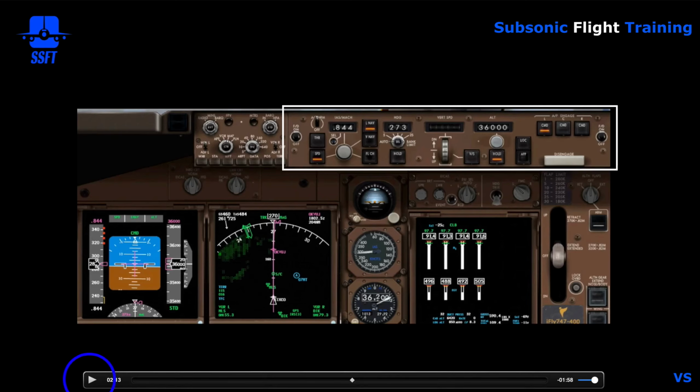This is in the iFly 747-400, and here's another problem with the iFly simulation. That's normally not allowed. You can't just reach up and push a center autopilot and the center autopilot will engage, or push the right autopilot and the right autopilot in command would engage. You have to disconnect an autopilot and then reconnect another autopilot in order to change autopilots. So this is actually a minor problem that's not correct in the iFly 747-400 simulation, and that's that you can reach up here and simply push a selector to change autopilots.